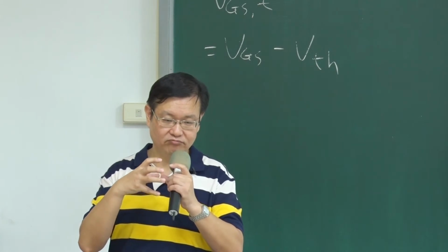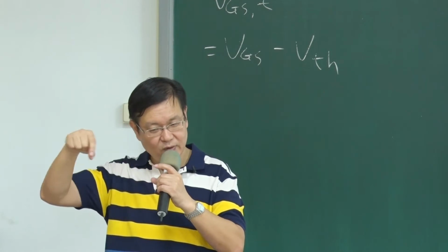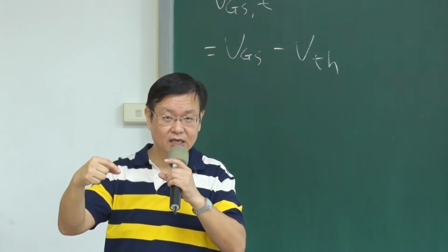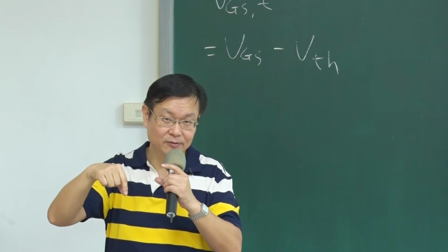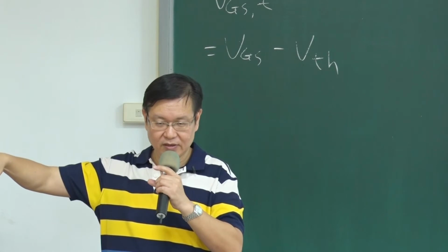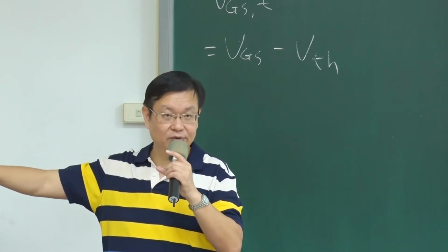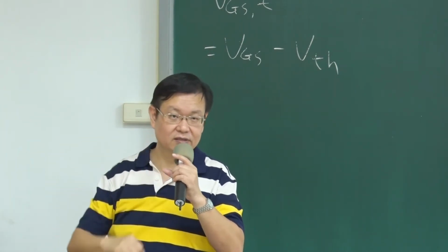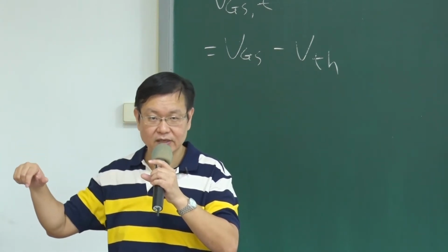Sometimes your device is only like tens of microns overall in size, and the wire you connect is only like several microns, like 2 microns, even 10 microns maximum. However, you cannot connect the outside large wire to a 10 micron wire. So you need to extend the very narrow wire to the boundary of the chip and open up a large area for connecting your real wire to the device. So those regions we call the pad, bonding pad, for wire bonding.